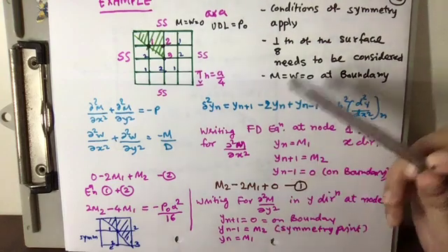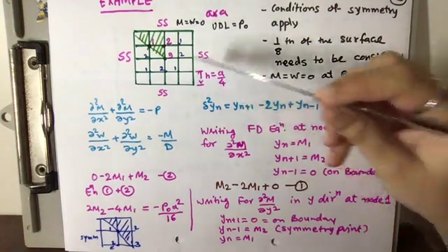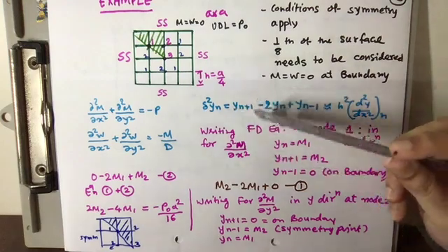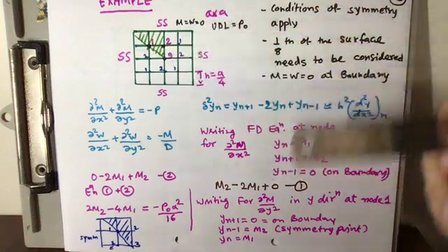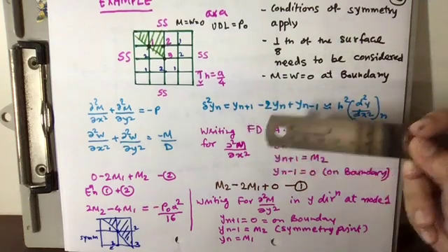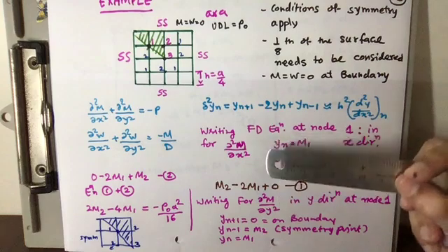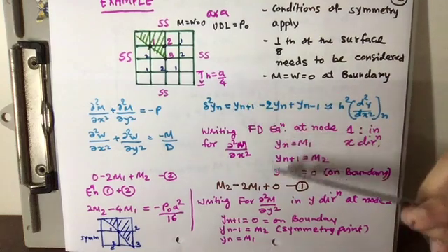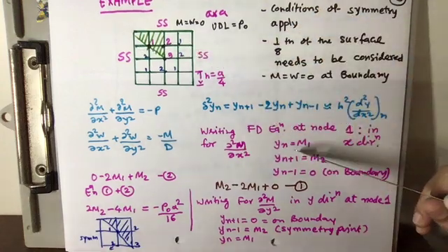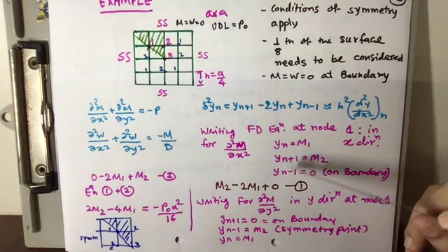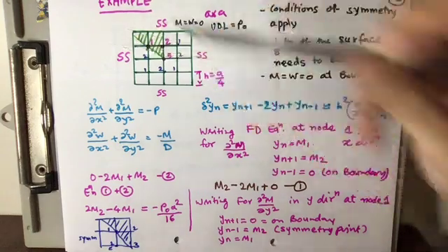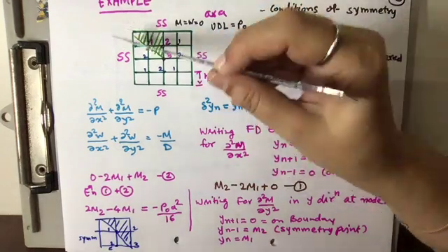We simply use this equation, denote the nodal values, because this is written in a general standard format. We convert that into our moment and deflection values, designating some values of moment and deflection. Deflection is nothing but a function, so function values are being replaced with the function we want. So we will replace yn as m1, because I want the value of m1 here. Then the forward value yn plus 1 will be m2, and yn minus 1 is the left hand point, which will be somewhere at the left.